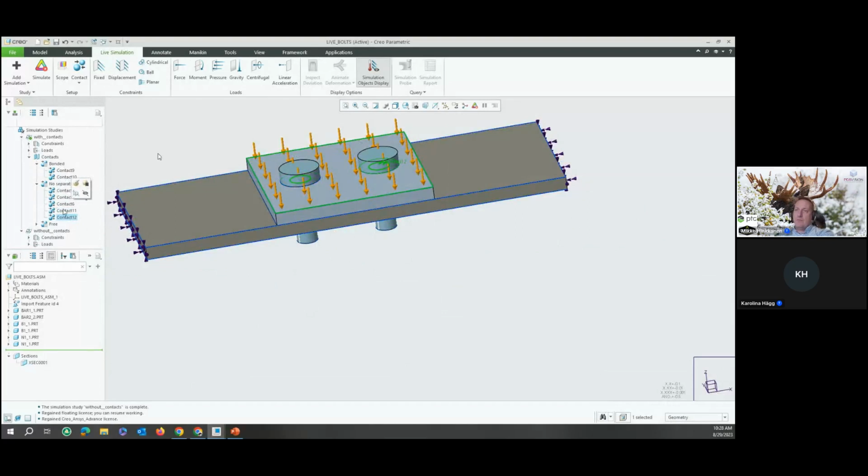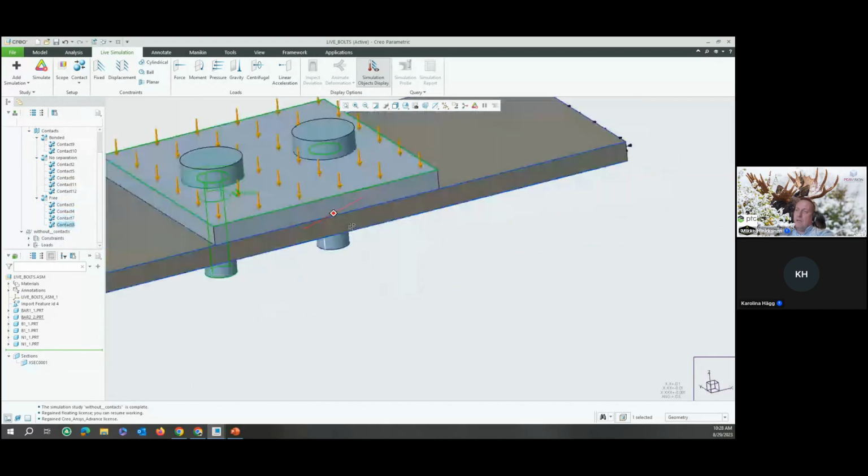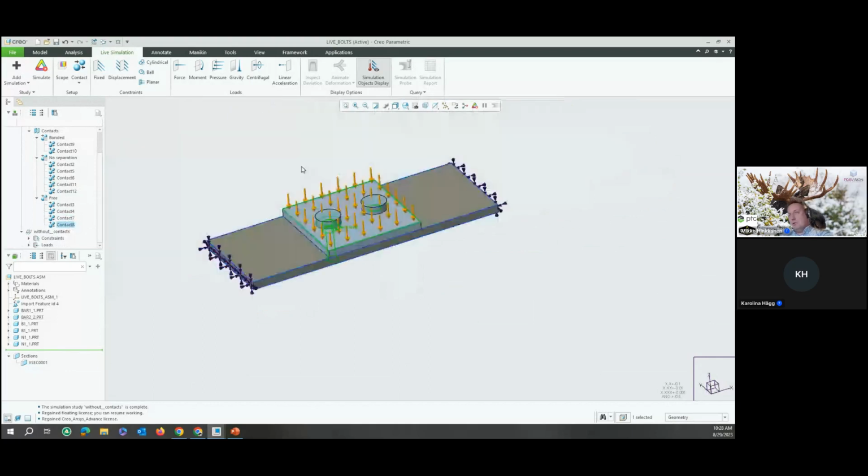And then we have some free, we don't really care kind of a thing. So, let's say no interaction between the bolt shaft and the hole. So they don't even know that they exist in the computational model. So there's a free, everything is free. You don't really see anything happening here. And same thing on the upper edge and upper in here. Now that is pretty much a contact definition.